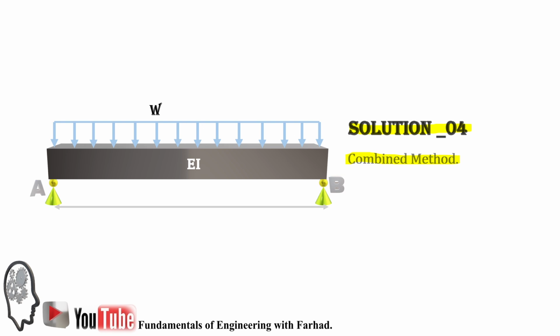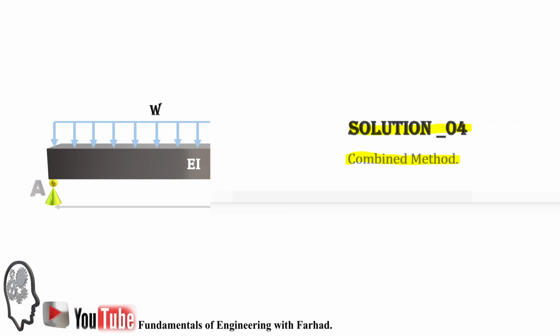So in solution 4, we remove half of the beam and use a sliding support at its center that allows the beam to dive down to the delta maximum. And definitely we know R sub A, since each support handles half of the load, which is WL over 2.